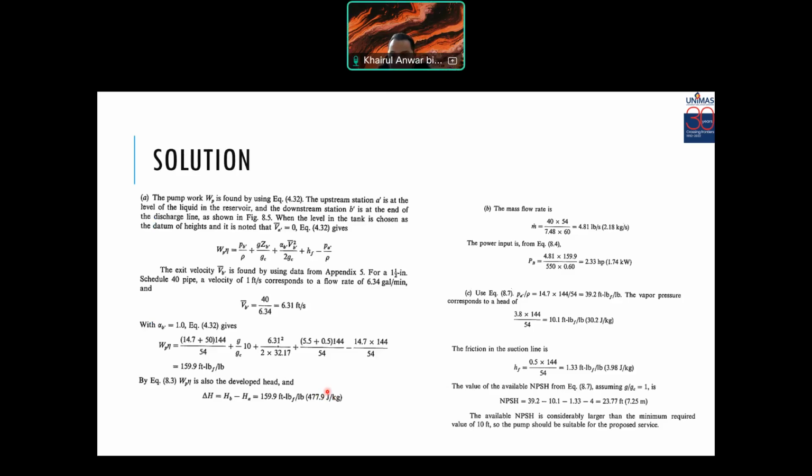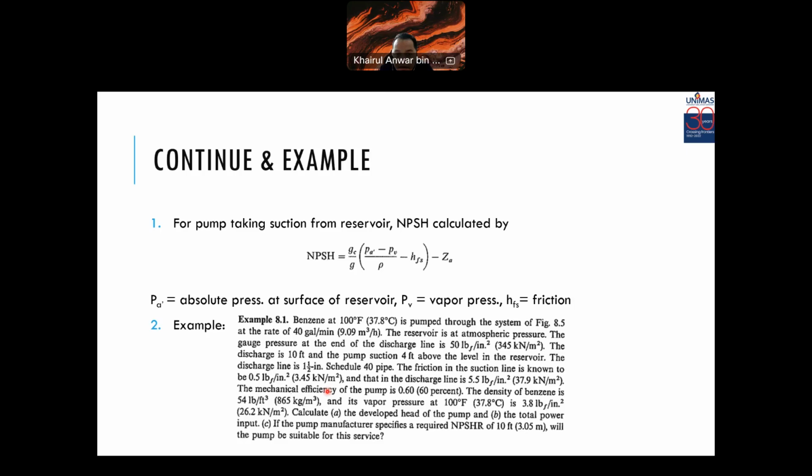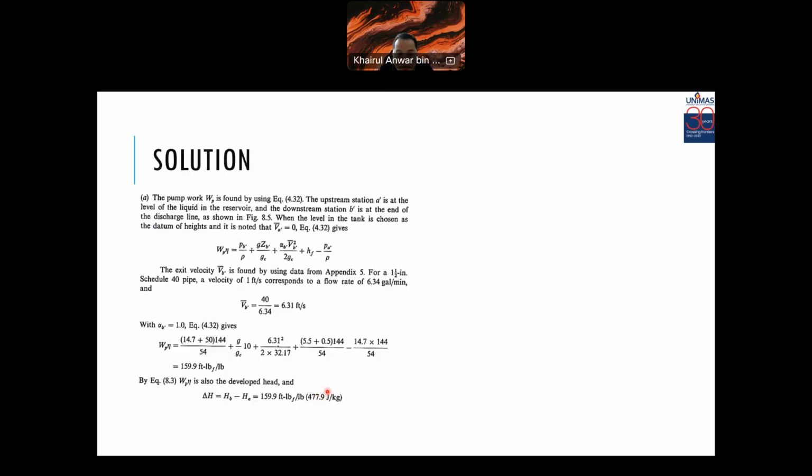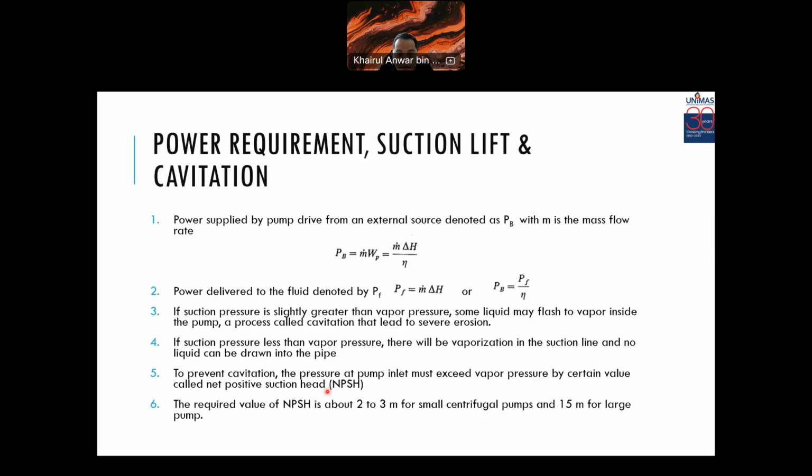Next is the mass flow rate. The mass flow rate is 40 times 65 divided by 7.48 times 60. Refer to this equation. Yes, so the number.